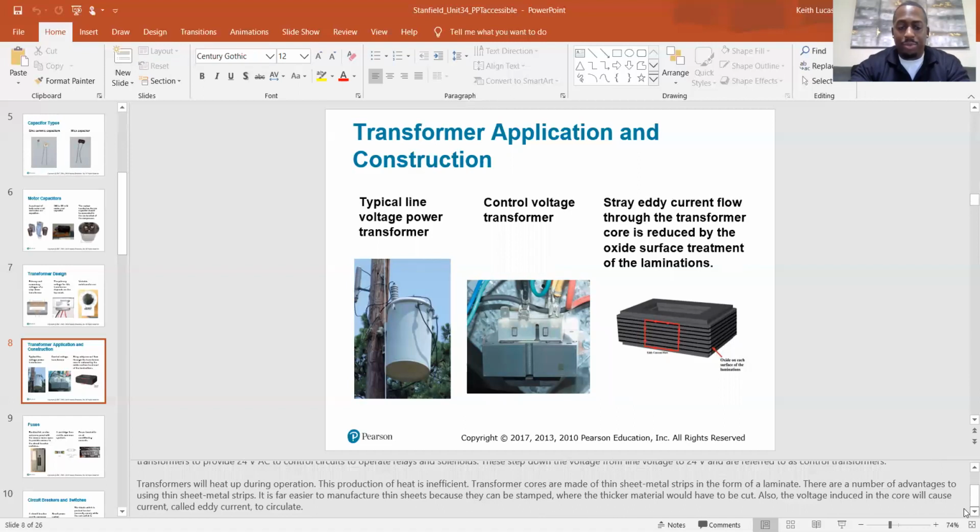We kind of touched on that before, but basically, if you have a 240 volt condenser outside, you still need 24 volts to activate that coil. The 24 volts is your control voltage. That's what's going to close and open your contacts. You have 24 volts going to your contactor coil, it's going to close the contacts and allow the 240 volts to pass and energize the condenser. You take away the 24 volts from the coil, the contacts are going to open, and the condenser is going to cut off.